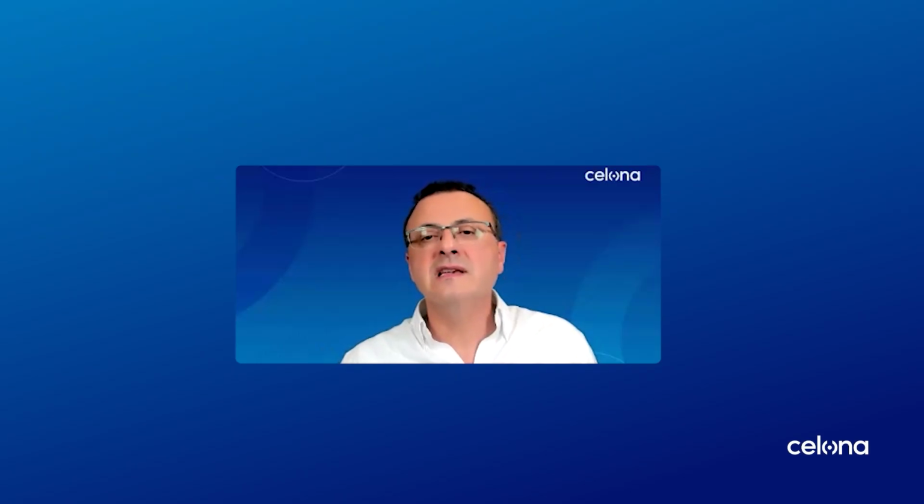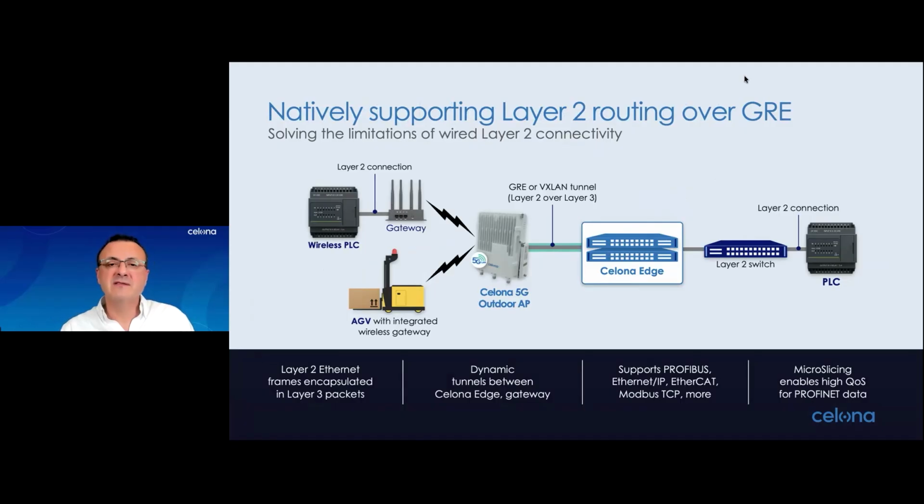Now, once you start connecting these devices through gateways, the next challenge becomes, specifically in industrial environments, what happens to the devices behind the gateways? Do we have full visibility, right? Many of these devices are not even IP native, right? And they may be relying on layer 2 industrial protocols such as PROFINET, EtherCAT, EtherNet/IP, Modbus TCP, Profibus, all of those. In many cases, the PLCs and controllers on both ends expect to be on the same L2 domain, layer 2 domain. So that's where the traditional approach starts breaking down, and there is some ongoing work in 3GPP to support these use cases.